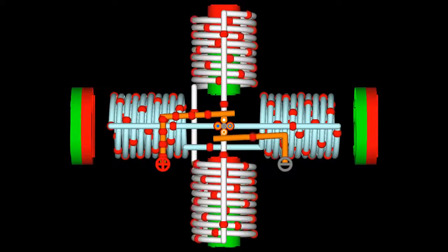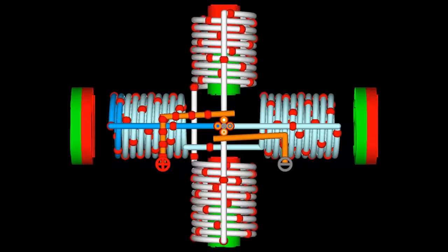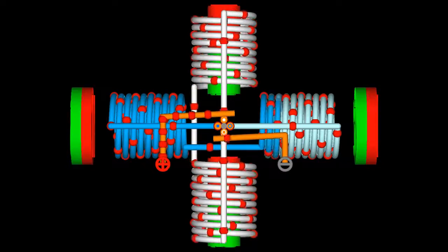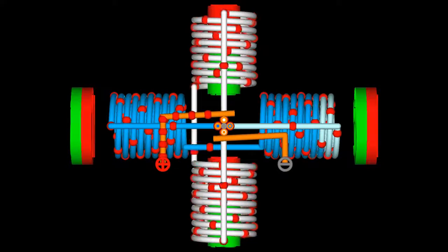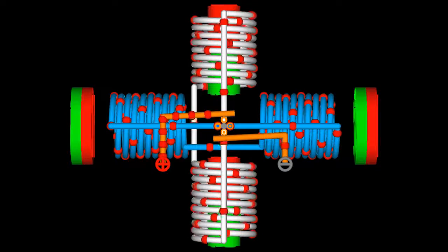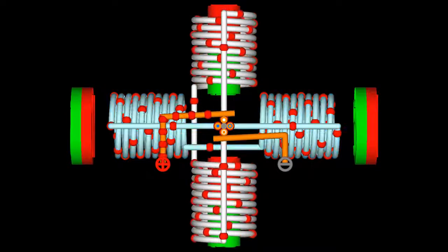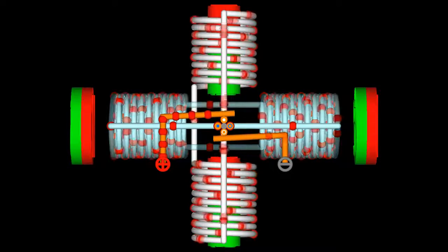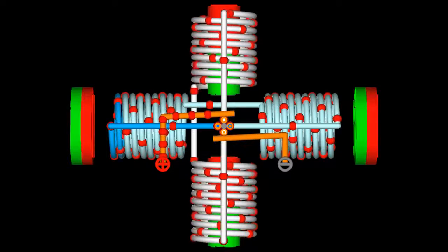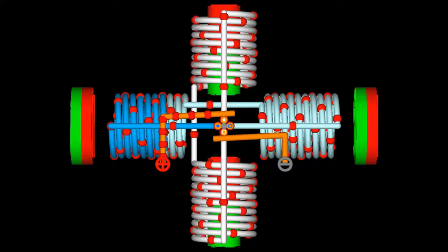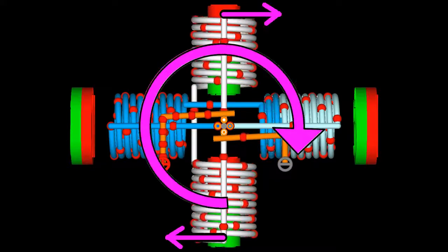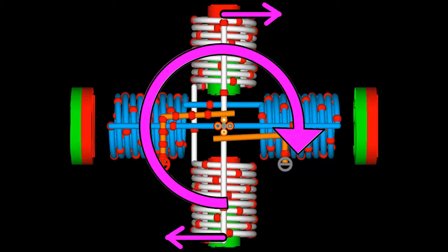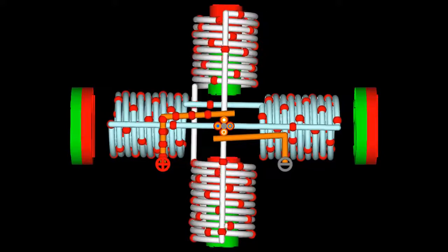What happens if one of the electromagnets is wound in the wrong direction? On previous animations, the wire ran from bottom to top at the front side of the light blue coils when going from left to right along the wire. Let's change that direction so that the windings run from top to bottom at the front view. Same as before, the north pole of the white electromagnet points to the top, causing a clockwise movement of the motor.